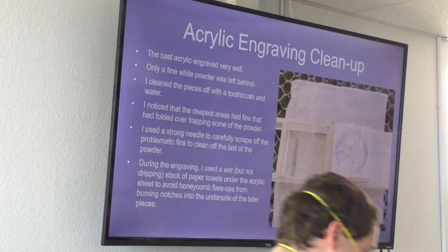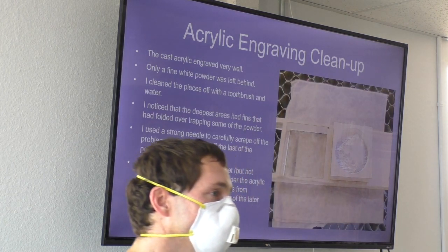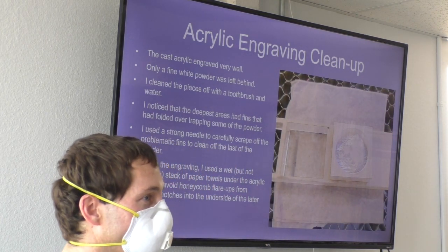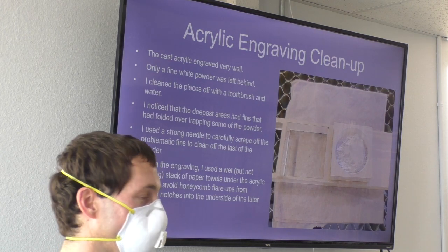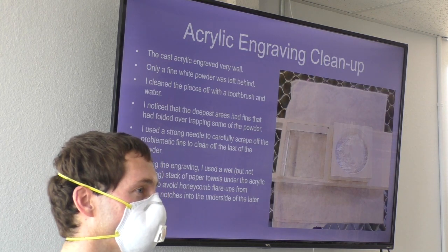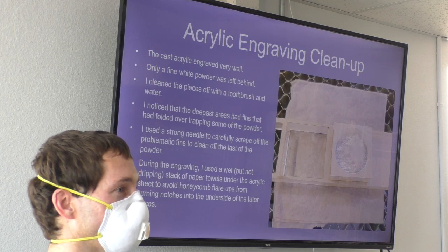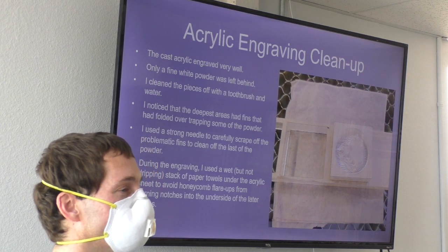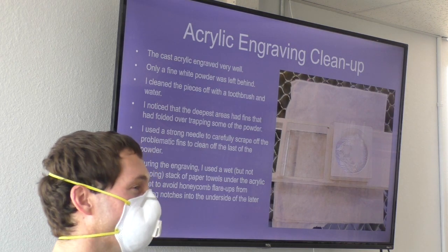So you cut the acrylic with the protective paper on both sides? Oh yeah, you don't want to take the paper off until you're totally done with it. Why not? Because you can scratch it. The acrylic scratches incredibly easily. Just rubbing a paper towel across it will scratch it. The only way I found to clean it is with a microfiber cloth. It doesn't like anything at all.